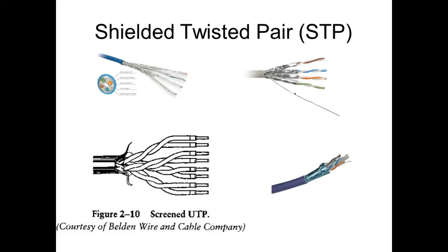So they have what they call this cable right here. This comes with our PLC. This is shielded twisted pair right here. And when we pass it around, you look, it's got this metal on it. And this is the shield. And if we went over there and looked at an industrial Ethernet switch, it's going to have a metal jacket on it. So what we do is we connect the shield through our switches and our devices, right?